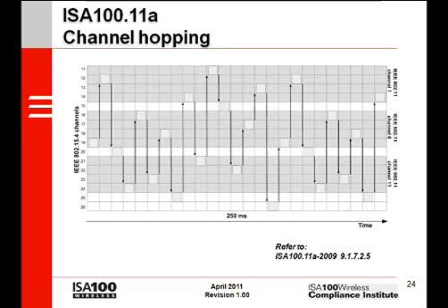This diagram shows one of the channel hopping patterns built into the standard. Time is shown across the bottom and radio frequency along the side. Each arrow shows a hop to another channel. Note that each hop changes the center frequency by at least 20 megahertz. Research and experience has shown that there is a very high probability of success using this approach. With channel hopping, each link becomes stronger. In practice, channel hopping results in a much stronger mesh network.